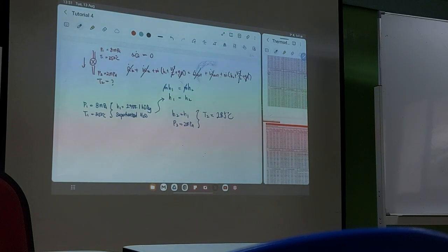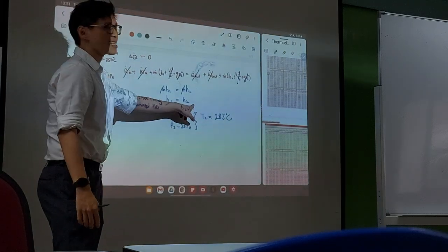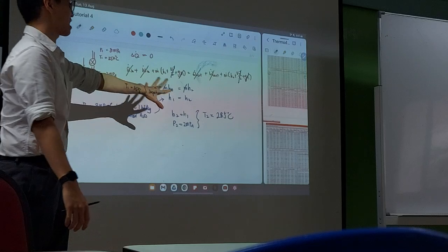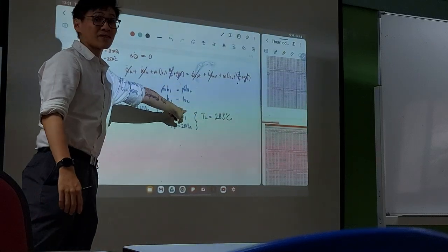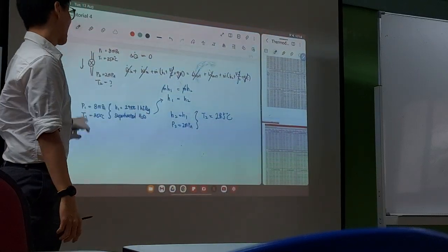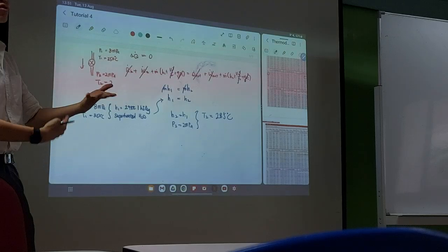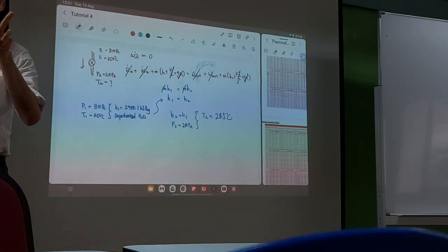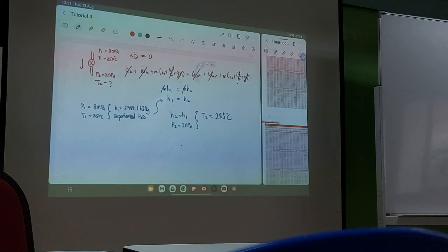So the whole demo is about you trying to find the connections between the states basically. Like what's the first one, what's the second one, what are their connections. So in this case, their connection is the initial enthalpy equals the final. So then you will always need to find out what are the two independent properties for each of the states. Then you can find the rest.